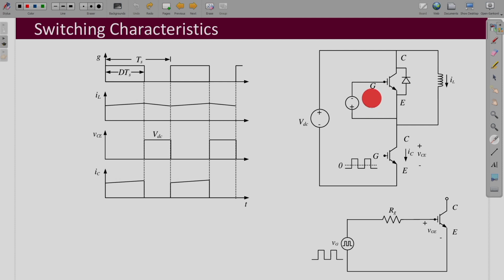So, the emitter is made positive with respect to the gate. So, this is turned off, which means it is blocking and is not going to conduct. It is only the antiparallel diode which we will be using for studying the switching characteristics of this IGBT, this lower IGBT. This is your device under test, many times also written as DUT.